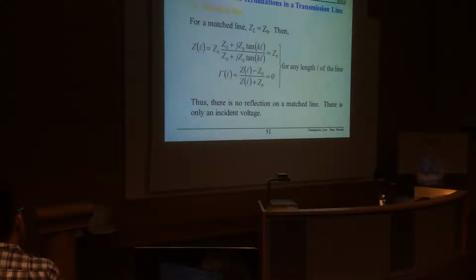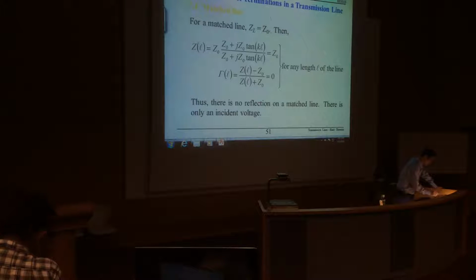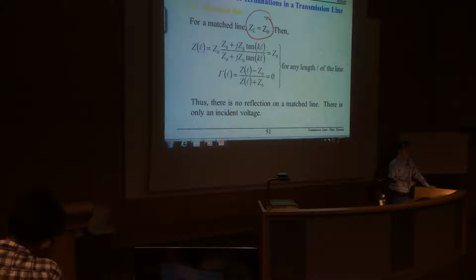Actually, a very important task for an RF antenna engineer is to design a good matching, so the antenna is well matched at the desired operation frequency. Matched means the load impedance is equal to the characteristic impedance of the transmission line.